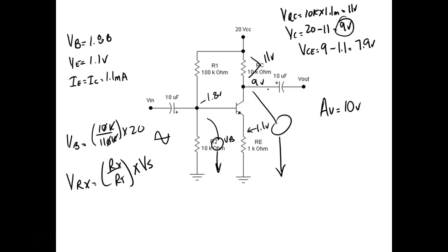And guys, this is something you really need to learn. So back in DC, what did you do when you calculated voltage drops? Well, you measured across the resistor. In troubleshooting, we very seldom measure across things. We measure from common, right? You understand that. So what that does is get a circuit common. It gives us the ability to take that black lead and put an alligator clip on it and clamp it on the common somewhere. And then now we're only probing with one lead, right?